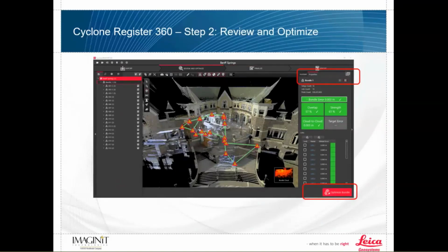I set my UCS, if I want to set a UCS here, if I want to clean point clouds here. If I've got some point clouds that maybe I captured with a BLK, and I want to combine them with the data that I captured from the RTC, well, this is where I would do it. I could select those 2 scans, visually register them together, move on.